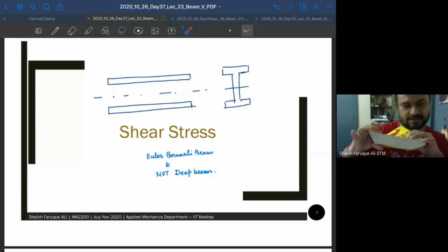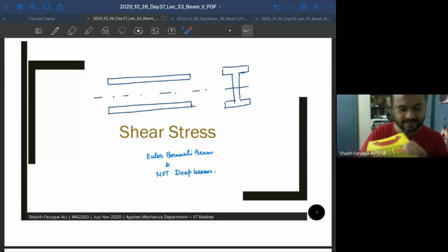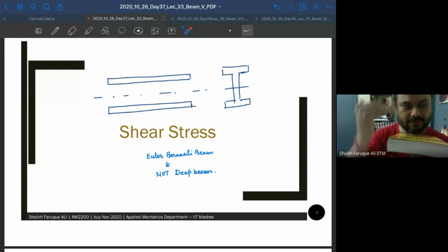They will start going out from each other. The reason being that each of the layers, when you bend it, tries to move apart, right? So we said that each of the layers gets strained, right? And when each layer gets strained, they try to hold on to the other layer, the one on the top or in the bottom. And when they go out from each other, they put a shear stress on those layers, the layer above and the layer below, right? So,